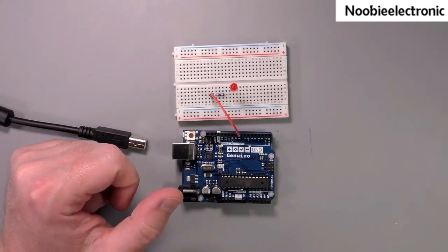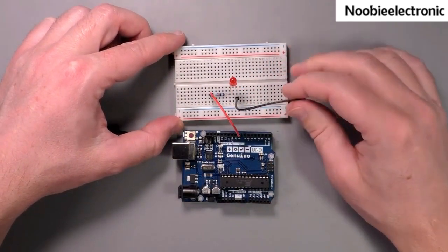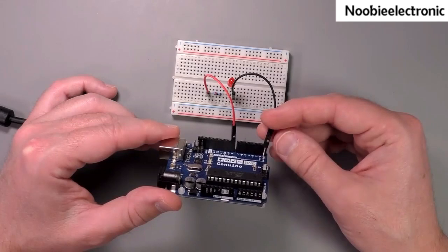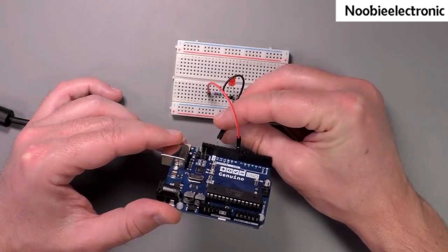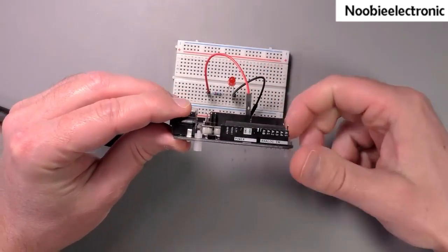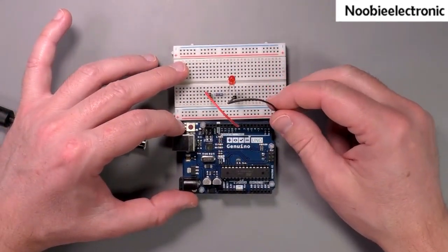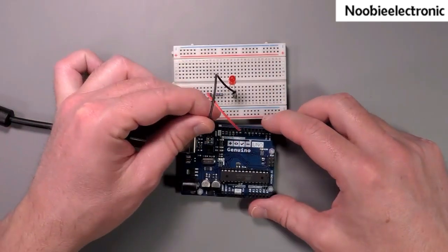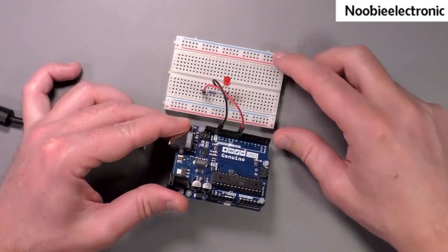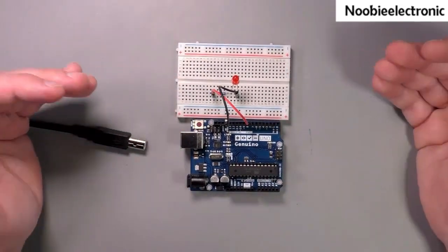Now take another jumper wire, connect it to the cathode of the LED, like that. And then this wire has to go to any one of the 3 available ground pins on the Arduino Uno. So we've got a ground pin right here. We also have ground pins here on the short header, the power header. Since we are working with digital pins on the long header of the Arduino Uno, rather plug it into this ground pin so it's closer right here. So I don't have to stretch the wires too much. Alright, so our circuit now is ready.